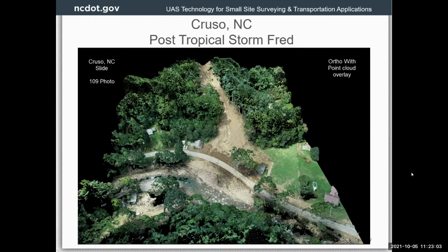The guys flew this in a three-dimensional checkerboard flight plan with the camera in an oblique position, not looking straight down, and they were able to get some of the surface underneath the trees. So in the point cloud, you could take the tree out and you still had a surface underneath. Usually you can't do that too often on heavy canopy, but those trees just had high leaves on them and trunks going down to the bottom. Next slide, please.